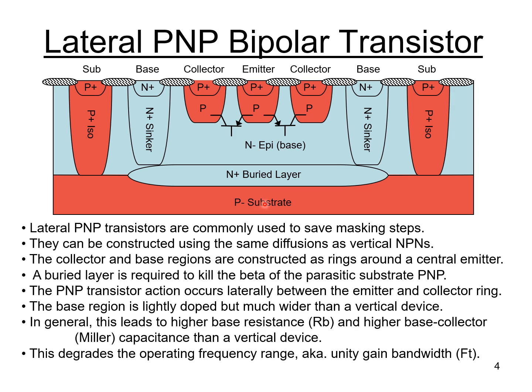So there's your PNP transistor. It's not really drawn schematically on the drawing here, but there's a parasitic transistor that you really don't want turning on under normal conditions.